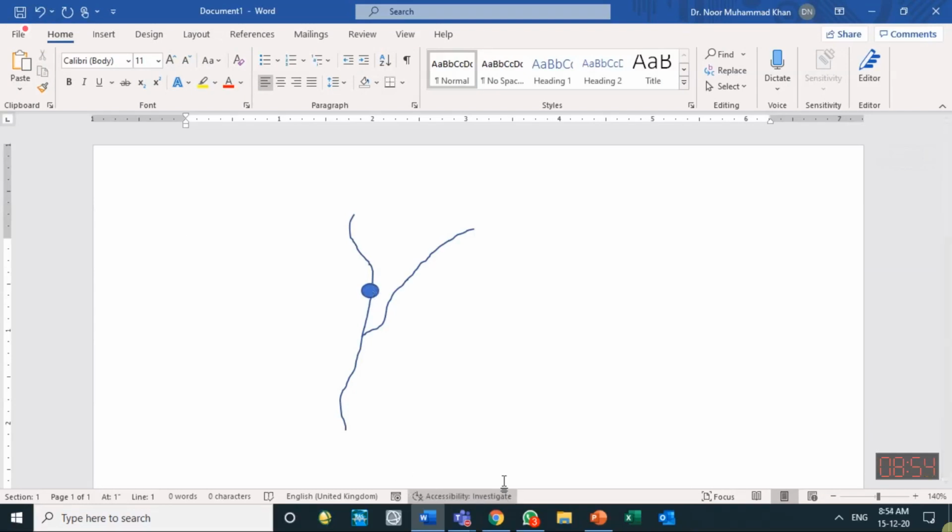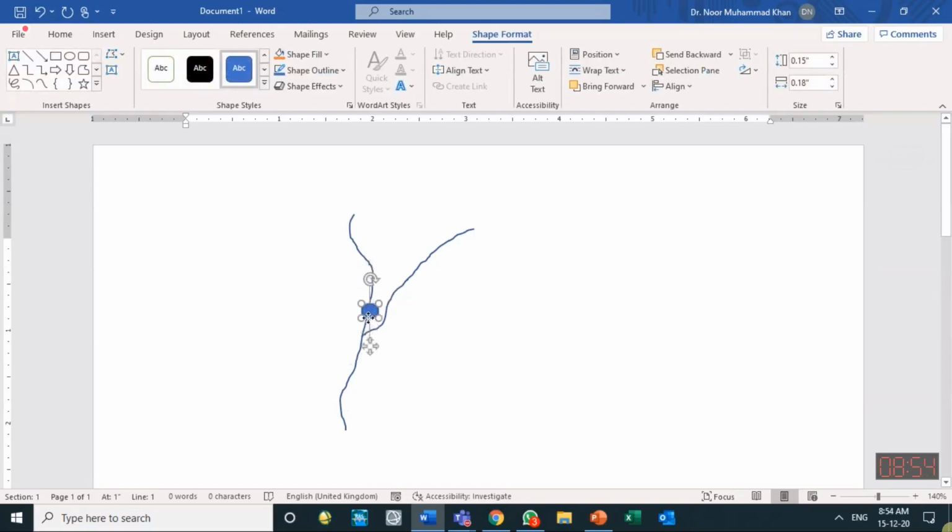We will be giving the wrong information that this tributary is having higher flows. So that is the reason, if this is the case, we have to move this station either to the downstream of this confluence, or we have to move sufficiently upstream so that the effect of this confluence point is not there. Either we move the stream gauge station much higher so that the effect of this confluence point does not reach over there, or we should move it down.